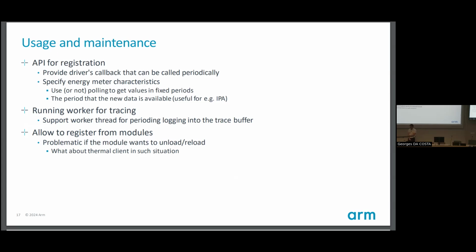Tough question. If we use this for thermal control, and the power actually consumed by the littles is affected by the DSU as well, we could probably just aggregate those two and live with that. The harder requirement would be fine-grained control per core. You would like to know how much energy you consume for each core while you run some workload. This is really tough because I haven't seen hardware that can give you per-core energy information. Most likely you can measure the power rail.